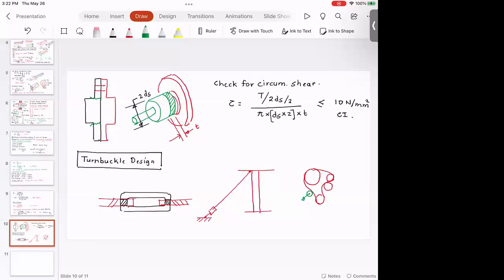So you can have a rope attached to a turnbuckle, and another rope, and say because of the heat, because of the application, because of the rain and maybe some other environmental factors, that rope plastically deforms. At that time, you can rotate the turnbuckle and still adjust the tension. You can take care of that slack. Everyone understood this? So turnbuckles are very important in mechanical design.